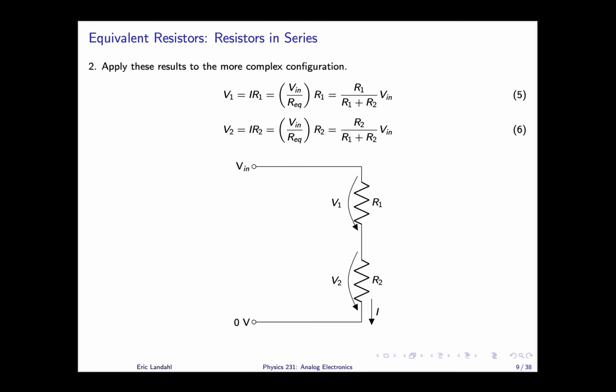Let's think for a moment about how exactly this works. Let's think about, in particular, just a couple of what I call limiting cases to see if it makes sense. By that I mean we're going to ask ourselves, what is V1 and V2 in situations where we already know the answer? Well, one of the easiest is if there's simply no voltage at all. We disconnect the battery or the power supply. In that case, V in is 0 volts, and 0 volts multiplied by this expression, whatever it is, simply gives us 0 volt output, which makes sense. If I don't connect the power supply, I read no voltage out. The same, of course, happens for the second resistor.